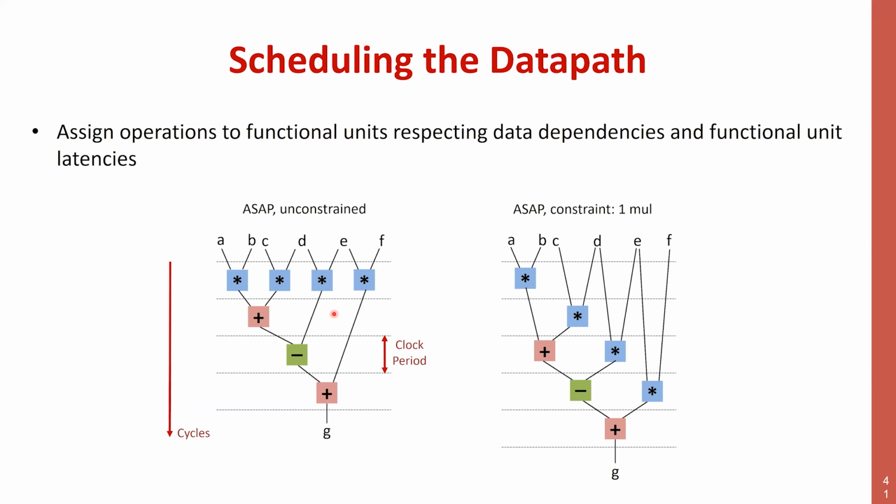If you look at what we are doing here, the first thing that you should be thinking of, hopefully, from the previous parts of the course, is that this looks remarkably like VLIW compilation, right? Somehow you have your 4 multipliers, you assign 1 multiplication to each, and then you schedule the addition on one of the others, and so on and so forth.